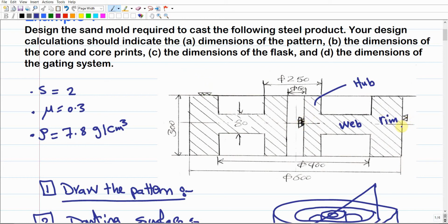As we discussed, machining in the casting process is a post-processing of the casted product. It means that once we break the sand and bring the cast out of the sand, it will have rough surfaces and it is very dirty. So we're going to do very quick cleaning, trimming of the gating system. Then we have to do machining for some surfaces. In some products, it is not necessary to machine all the surfaces.